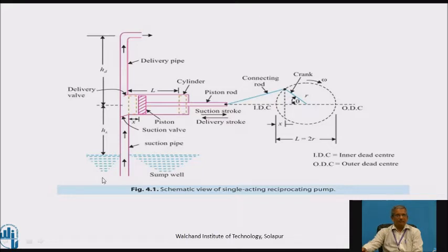This total head can't exceed the limit given by the manufacturer. So the lower the suction head, the higher the discharge head.